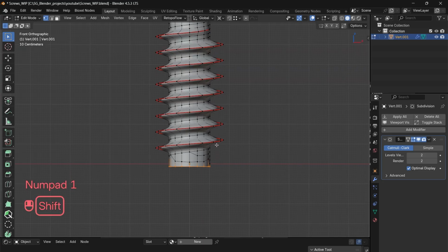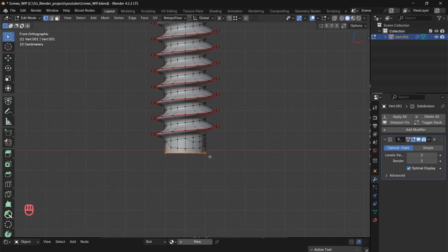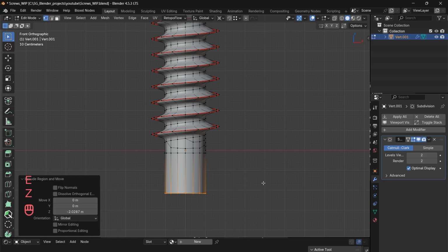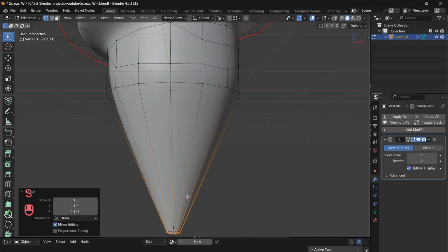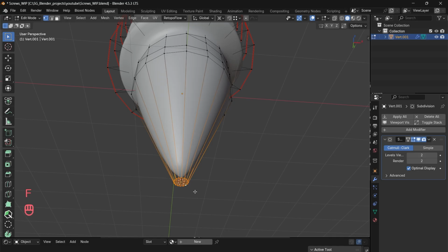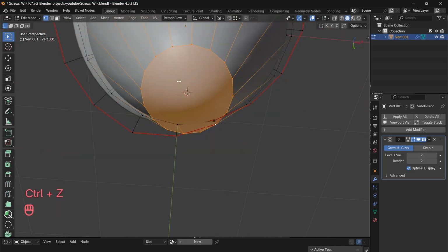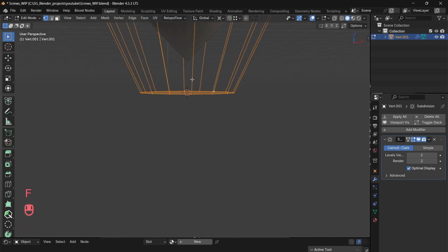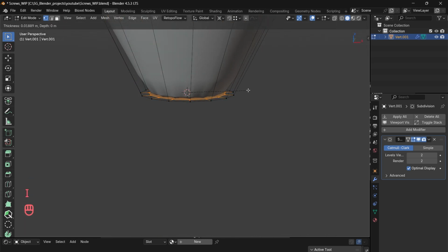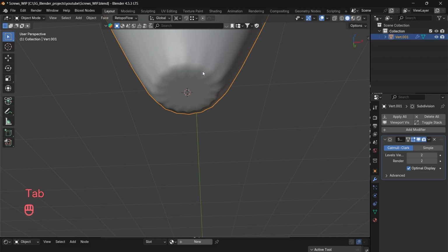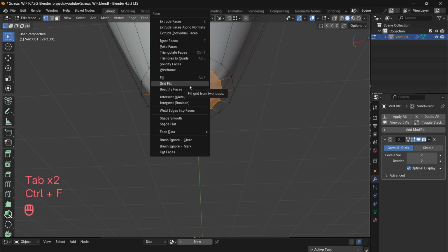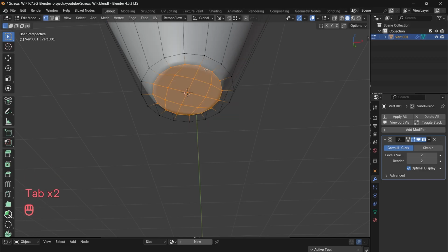Many people, what I have seen, just extrude this along Z, and if I take the cursor to this selected, as my pivot point is the cursor, they just scale it like this. This will cause this pinching effect. Others might add a face and just extrude it. That also causes a pinching effect. If you apply Grid Fill, that also doesn't look nice.